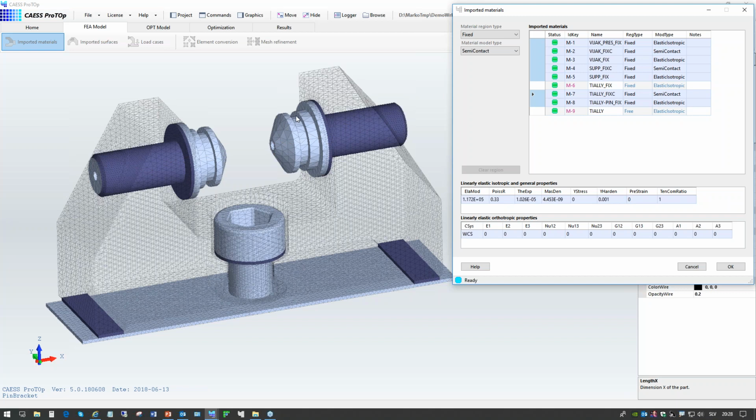Now, the usual way, if your optimizer does not offer something special, you would have to model this as usual contacts. This step is actually devastating in regards to performance, because the computation time is increased by an order of magnitude.